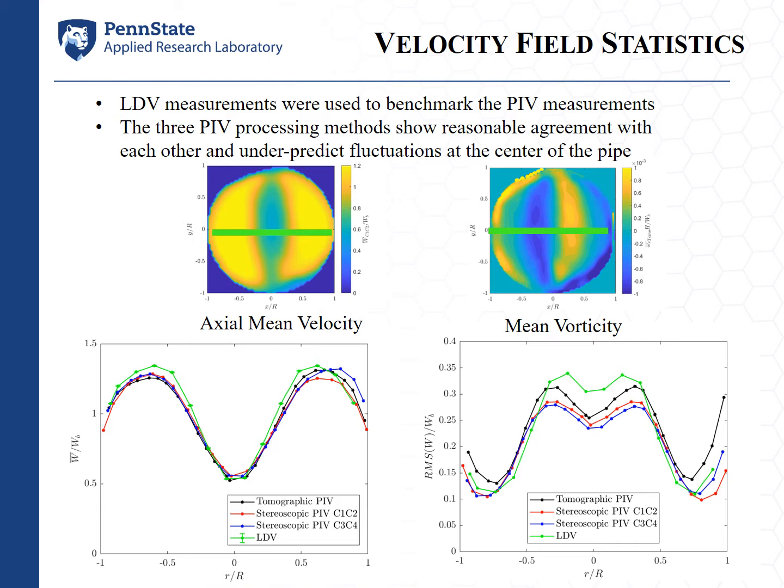but as we go away from that center line, where we have the least amount of distortion, we can see that all three of the PIV estimates start to underpredict the velocity field, and this could be due to two things. One, it's a shear layer somewhat in this flow, and PIV fields tend to underpredict the velocity in a shear flow due to a smearing effect, but it could also be due to the higher distortion that's characteristic at the near wall locations.